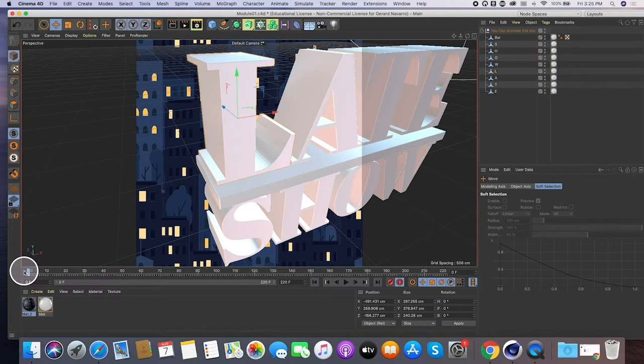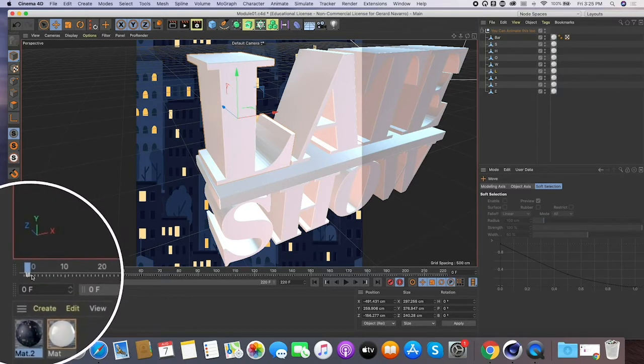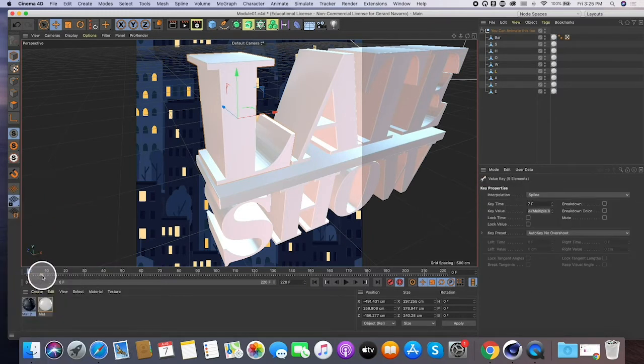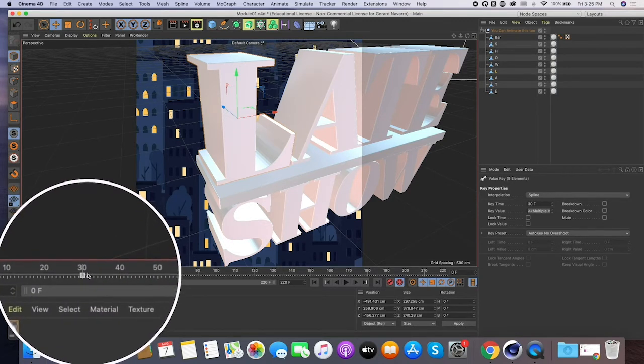Again, to have a complete animation, you need 2 poses, one before and one after. So this is our before pose. We can actually move this later on. Let's just click and drag this to our timeline. I'm imagining this is my last pose for my letter L, so I'm gonna move it maybe to the 30 frames mark.